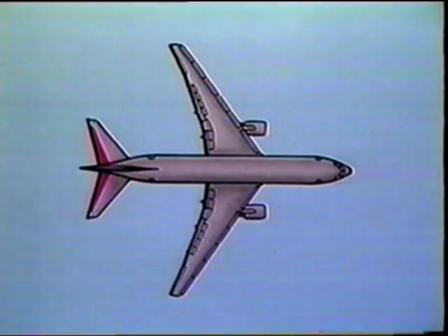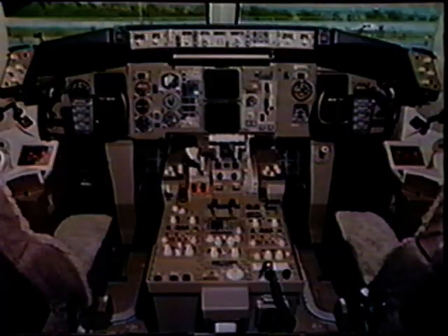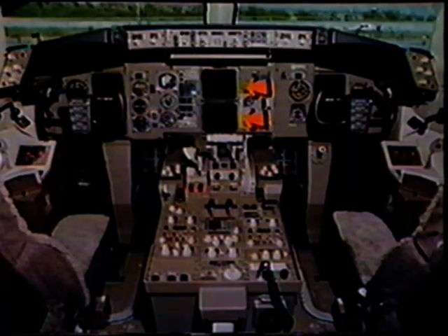The elevators are connected to the trailing edge of the horizontal stabilizer. They provide attitude control of the airplane about the pitch axis. The elevators are controlled by pilot input commands on the control columns or by the autopilot control system. Elevator system indications appear on the ICAS display.